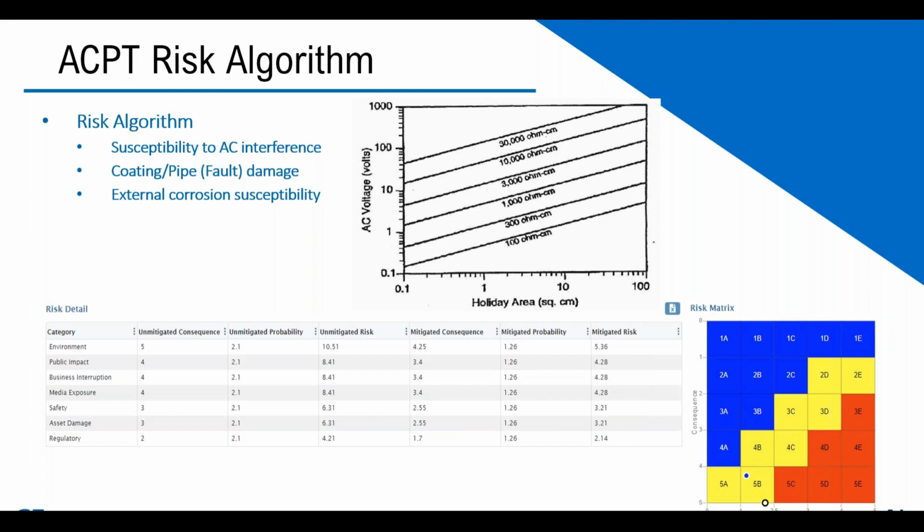You know what, 1,000 ohm-centimeter or above, and then the voltage has really got to go up before you have any kind of a problem. So if you're sitting at 50,000 ohm-centimeter, not an issue. If you're sitting at 10 million ohm-centimeter, the likelihood will be almost nothing.